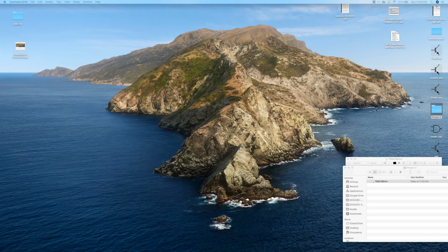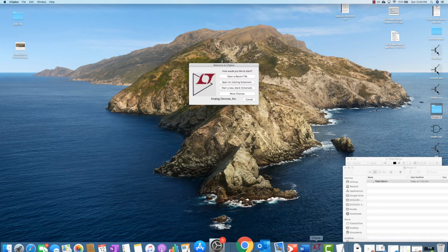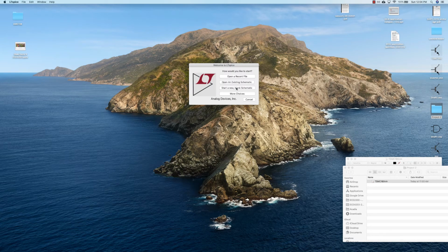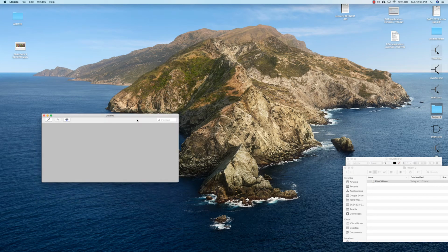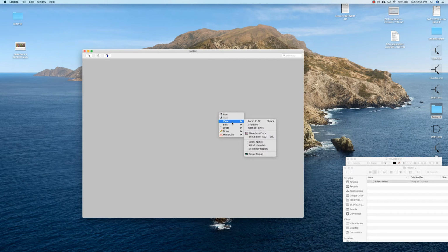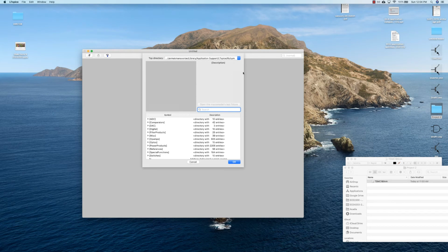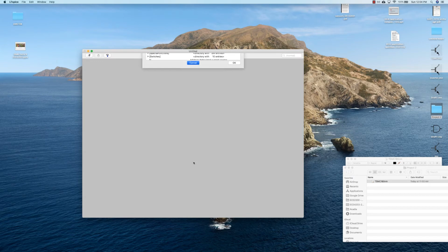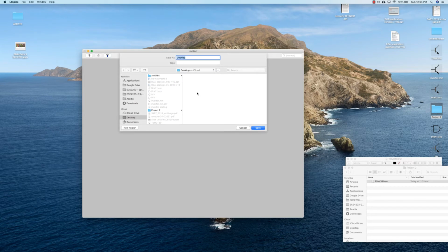Okay guys, so now we want to use the schematic that we just made. So I'm going to start a new blank schematic. Okay. Now, for whatever reason on the Mac anyway, if I try to put a component down without saving the location of this, it only goes to this top directory. There's ways to change this in the PC version, but I haven't been able to change it in the Mac version. So anyway, what I just did that fixed it, allowing me to get the right path, is I saved this in the same directory that I had put the basic inverter in.